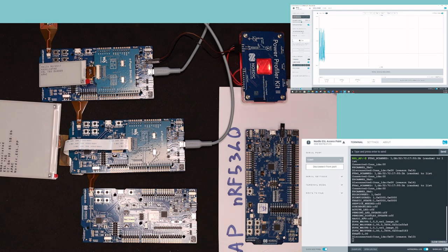Now we'll let the measurement go, and we will see exactly what is going on. As you can see, the tag is waking up around every 1.7-1.8 seconds. This is the periodic advertising interval in this case, and the tag is waking up for a very short period of time, and then after it wakes up, it listens for a synchronization packet from the access point, and then it goes back to sleep. So we can see that the average current here is around 5 microamperes. We can let it run to get more samples, and we can see that the current consumption is generally between 4 and 5 microamperes.